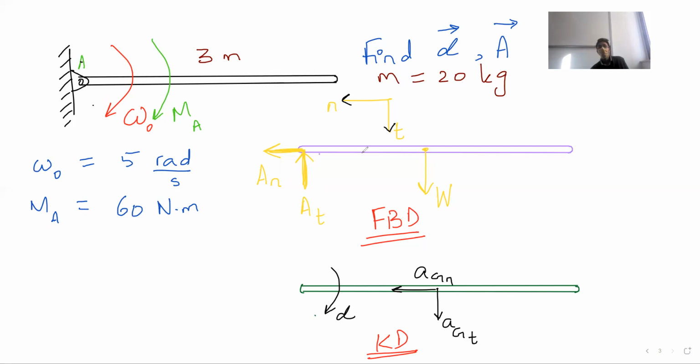Okay, after drawing, what exactly appears in the free body diagram: the reaction at the pin joint, the weight. You remove all the supports, you put all the external forces and moments. So I think I made a mistake here. I am also supposed to put a moment here. Everyone understand this, right? The mistake. Now, everything is in my free body diagram. The coordinate system, I think, is separate. You don't confuse it with this one.